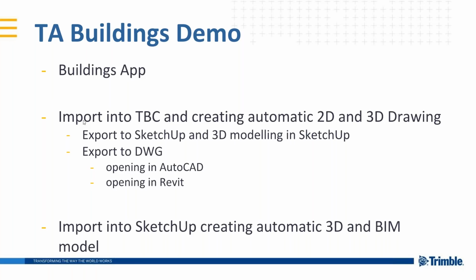And after that, we will import the job XML file into TBC, and we will see that we will create 2D and 3D automatically. But also for some of you that need to deliver this in a different format, we will export to SketchUp. Then we will continue modeling inside SketchUp, and we will export to DWG. So we will see how it's coming to AutoCAD, and also in the cases where you need to use Revit or any other BIM software, how we could continue from the data that TBC produced. And finally, importing the job XML file inside SketchUp, so we will get a full 3D model automatically.